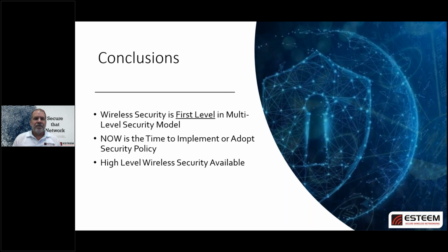Okay. The other thing that we can consider is, when we want to look at other frequencies, like I mentioned within the 5.8 gigahertz, we can also have a wireless network that is available just beyond Wi-Fi. We can use 900 megahertz with the Horizon 900. We can use one of the non-Wi-Fi channels of the 5.8, or we can simply lock out the Wi-Fi access into any of the radios, even the 2.4. So really it just becomes, what is going to be the best for the application and for your needs.